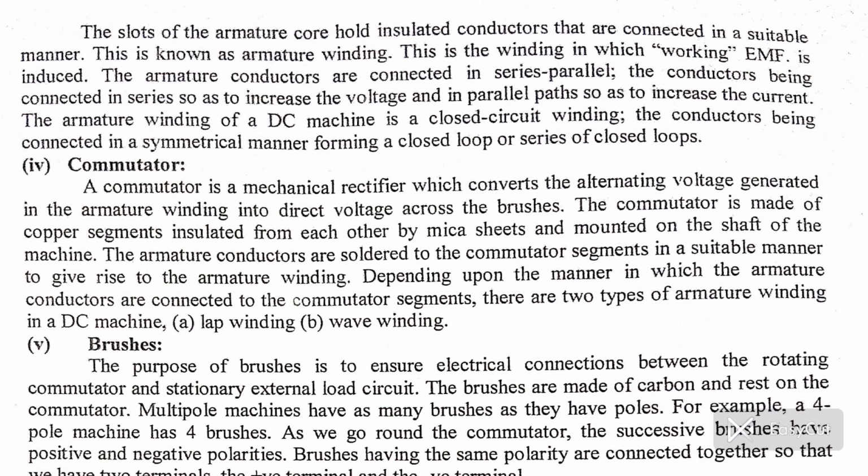5. Brushes, and finally, the brushes. These are usually made of carbon and rest lightly on the rotating commutator. The purpose of the brushes is to connect the rotating commutator to the external load, to transfer the generated DC voltage.